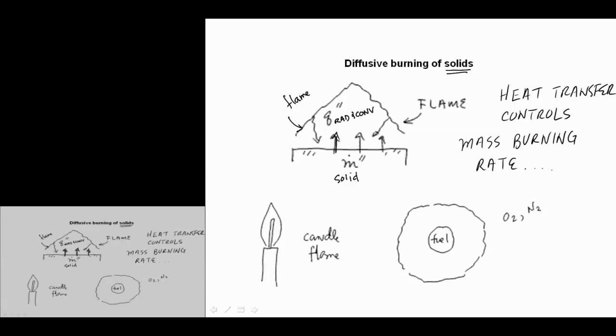That mass flux that we've talked about before is of what might be called a pyrolysis gas, might call it a pyrolysate. So it's the gases that are evolving from this decomposing solid that are the fuel that burns at the interface with the oxygen. So the fuel that's liberated by the thermal decomposition of the solid burns at an interface with the oxygen that is external to it.